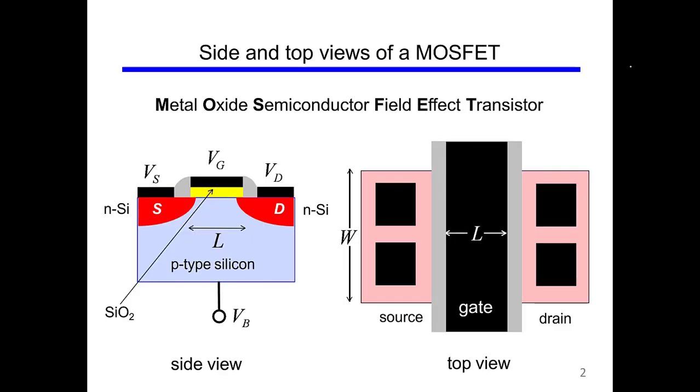So this is the three-dimensional structure of a metal oxide semiconductor field effect transistor. Until now we have been drawing the transistor like this. So this was our drain, this was our gate, and this was our source. We have been purposely neglecting the fourth terminal. The fourth terminal is drawn somewhere like this, and it is called the body terminal. The voltage applied to the body terminal is called VB. So we have VS, we have VG, we have VD.